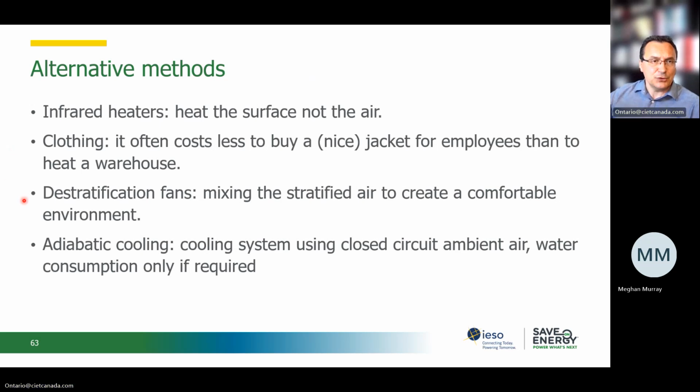Destratification fans. We know that in high ceiling areas, warm air will rise and will create a differential temperature across the height of the space. So using destratification fans properly can increase the mixing and controlling destratification for an effective operation of the space.